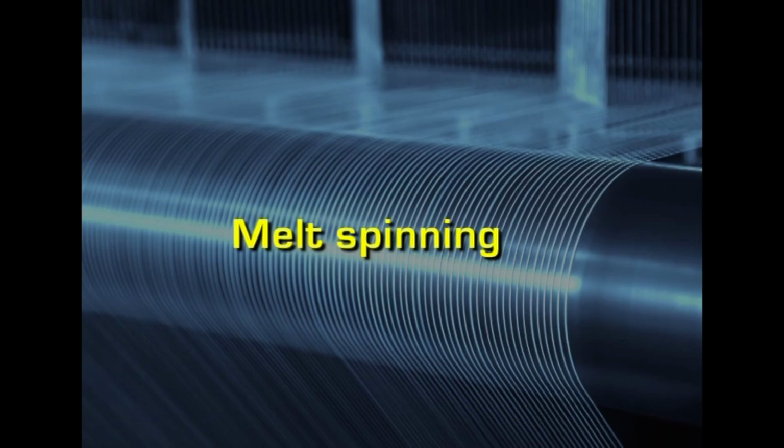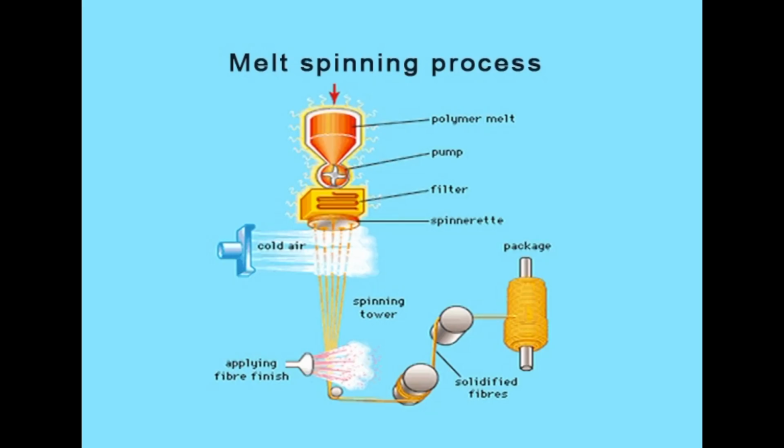Melt spinning is the simplest method, because it involves only melting the polymer, extruding it through the spinneret and then cooling it in air. When it hits the air, it gets cooled and solidifies in the form of a very thin filament.